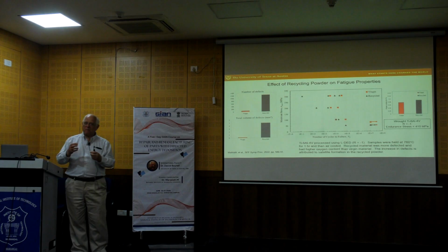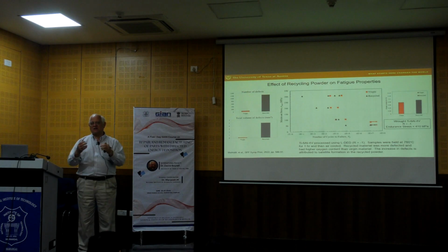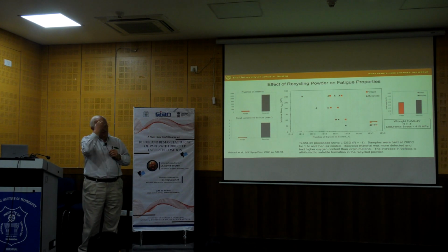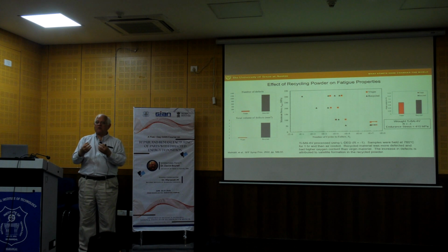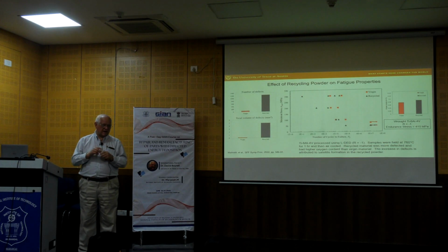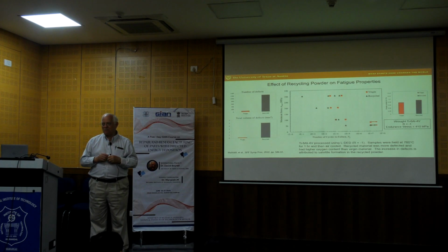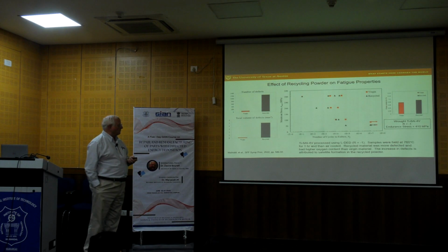We don't see that here, but basically it's attributed to what we call satellite formation. What this is, basically, is that the powder that goes into the beam during the laser DED has particles that will stick together but don't flow into the melt pool. And so we have particles that are stuck in the recycled material. What that does is change the aspect ratio from spherical to something non-spherical, which always has a negative impact on the packing density and other aspects associated with the powder.